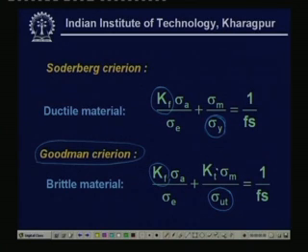However, we are multiplying an additional thing, that is Kt, with the mean stress, whereas we are not multiplying Kt with the mean stress for the Soderberg criteria.